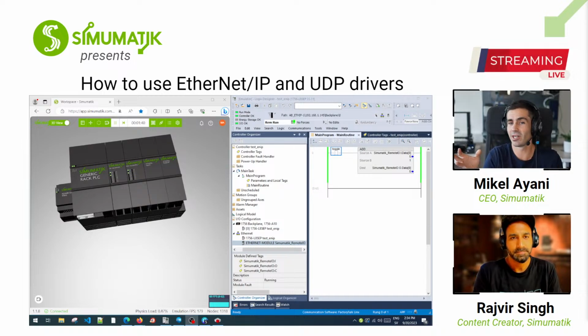Of course it requires more work because we need to set all the IPs in our computer, but suddenly our computer will emulate all this architecture with several remote I/O modules, which makes everything more transparent, because the model actually represents reality more accurately and allows you to test that you have all the IP addresses set up correctly, the sizes of the telegrams, and so on.